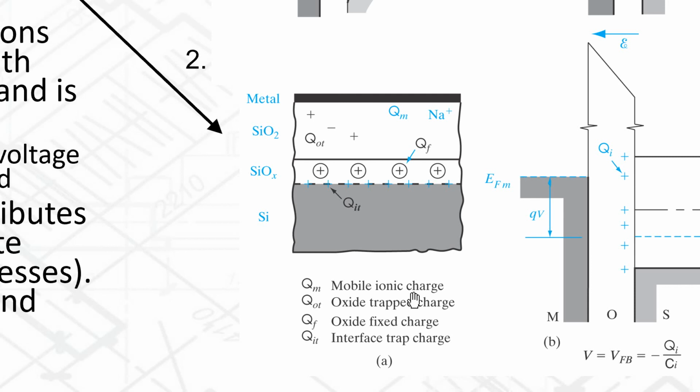There's a process in semiconductor fabrication called wet etching, and there's also a process called rinsing after you do your photolithography steps. So these are both steps where the semiconductor material, the wafer, has to be placed in a liquid. That liquid could be a chemical etchant, which removes oxide, so it's some type of acid, or it might be a photoresist remover, which is also an acid or base type material that is used to remove photoresist after a photolithography step.